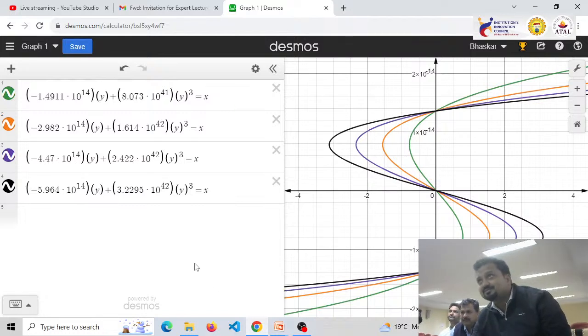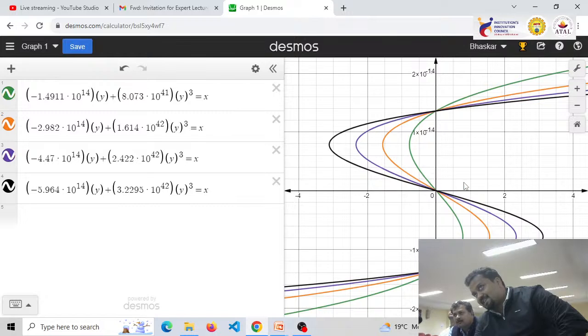So the same phenomenon is happening in the reverse direction also. As I am increasing the reverse voltage, the value is increasing. That's why you have taken the magnitude part. Yes, in the negative part. Here also you see, it's falling. The gradient is negative here. So that tells me the presence of negative capacitance over here.